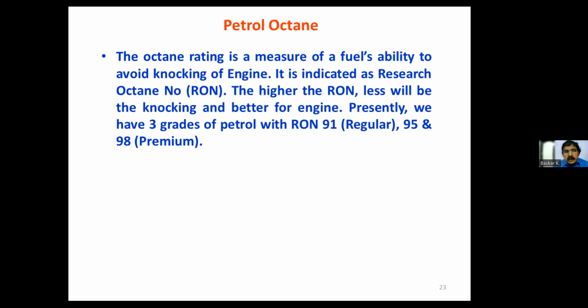The octane rating is a measure of a fuel's ability to avoid knocking in the engine. You can see the engine, petrol engines are basically 2-stroke or 4-stroke engines, where the movement of the engine is taking place, right? So that movement will give you a knocking sound, right? That knocking is measured as the research octane number, RON. We call it RON. The higher the RON, the less the knocking and the better for the engine, but not better for the buyer's pocket, because higher octane petrols are always costlier.